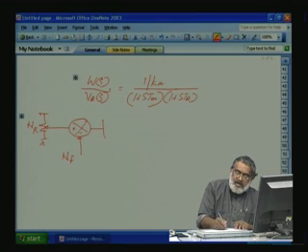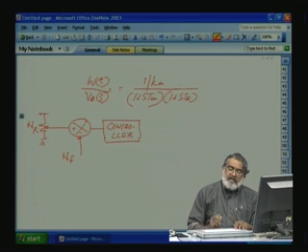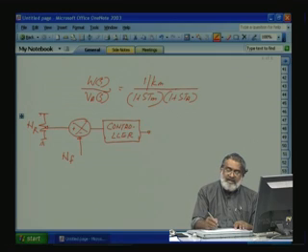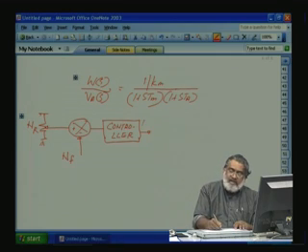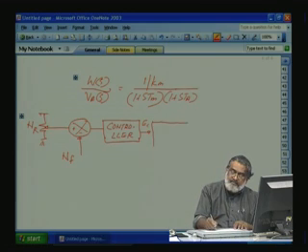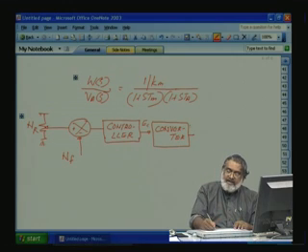So, this will go to a controller, this controller output will control our firing angle. Let us say the firing angle cosine comparison EC. This we have to give to our converter. This converter output gives the required Va, armature voltage, and this we are giving to the motor.